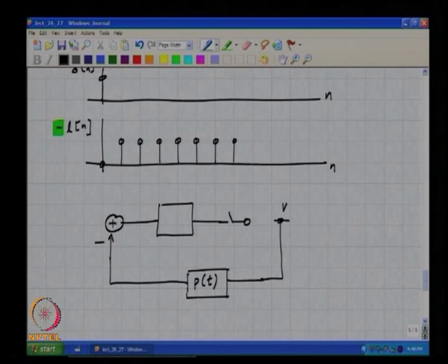You understand? So, let us take an example of an NRZ pulse shape for the DAC. We need to talk about some pulse shape instead of leaving it as P of t. Let us call this an NRZ DAC, and to make matters simple, let us assume that the sampling rate is 1 hertz.